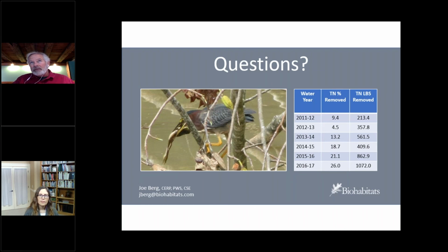Typically, that would still work, but what you end up doing is diminishing the value of that because of the groundwater. Basically your hyporheic bed would become saturated with shallow groundwater, and most of the treatment water, if you're trying to treat the pulsed surface water, would be running over top of that groundwater saturated material.